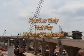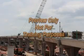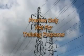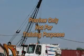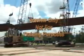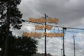There can be many life-threatening hazards to be aware of during the operation of a crane and the lift. Some of the possible hazards include power lines. When operating a crane or doing a lift near power lines, always assume they are energized. If during the operation of the lift, any part of the crane, load, or load line could get closer than 20 feet to a power line, safety precautions must be taken.